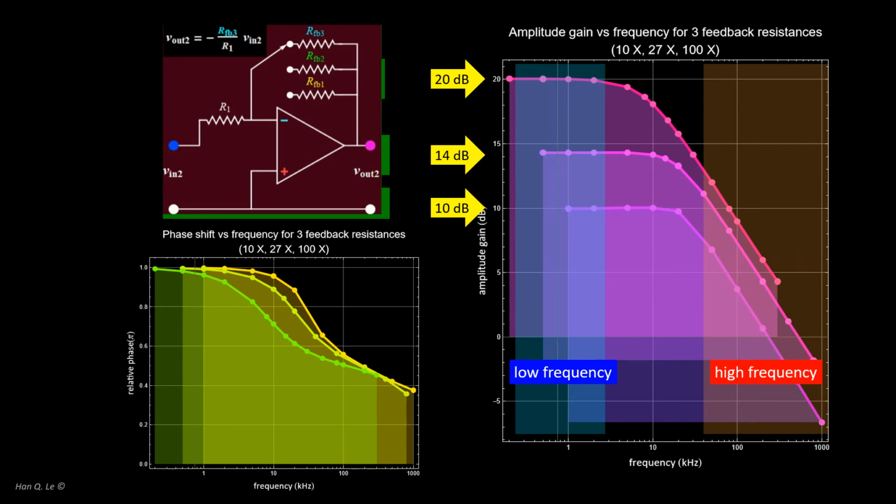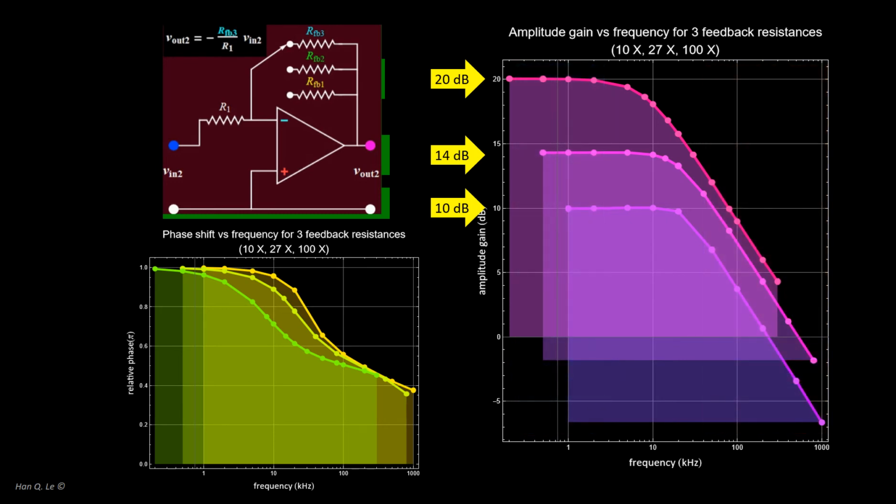For each gain setting, there is a range of frequency, called bandwidth, for which the response is roughly flat. Notice that higher gain is associated with smaller bandwidth and vice versa. This is known as gain bandwidth trade-off. One cannot have both. Either high gain and accept low bandwidth, or have high bandwidth at the cost of low gain. Bandwidth is a concept, not a rigorous quantitative definition.